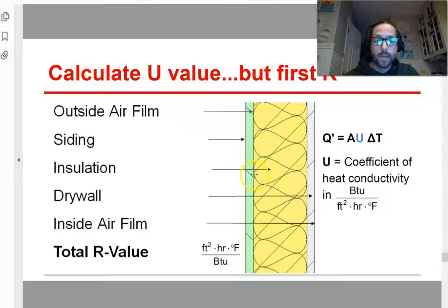So in order to do that, you need to figure out the U value of all the different surfaces, the walls and the ceiling and the foundation and so forth, and then figure out, in a typical year, how much heat is going to go through that, and that's how much heat you have to replace over the course of the year.